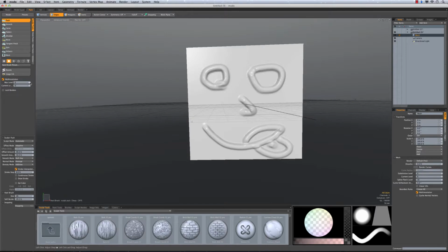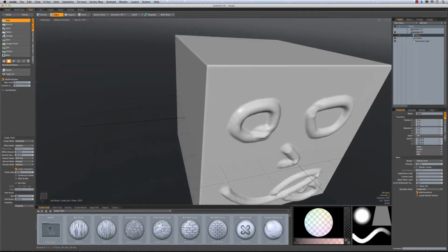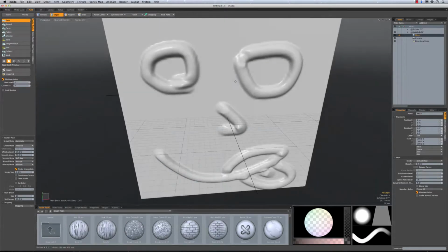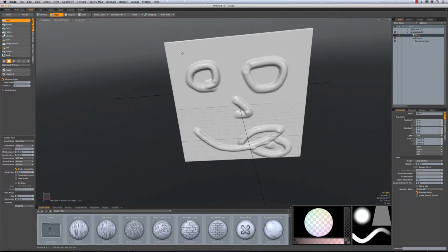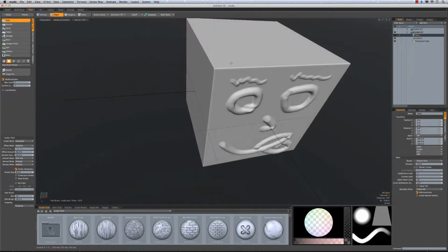You can also step up in subdivision, knowing that you are going to start to introduce some slightly rounded corners, which obviously could be all right depending on what you're working on, and then work at a higher level of sculpting. Of course, if you have a tablet plugged in, that will work significantly better. This also gives you the benefit of being able to adjust the edge weight using sculpting as opposed to just using weights.